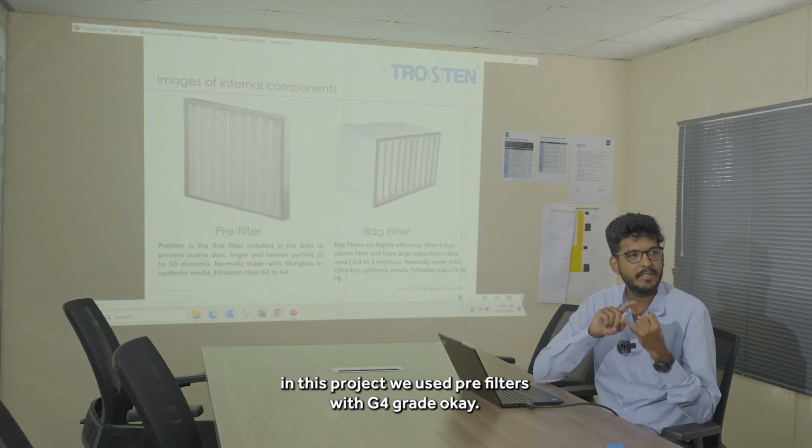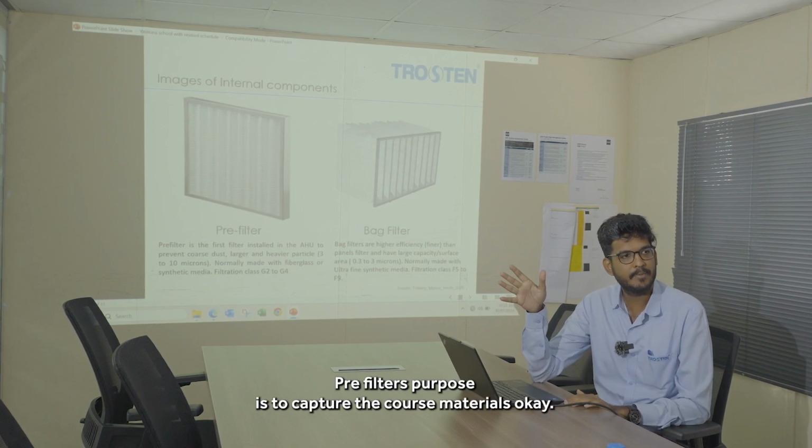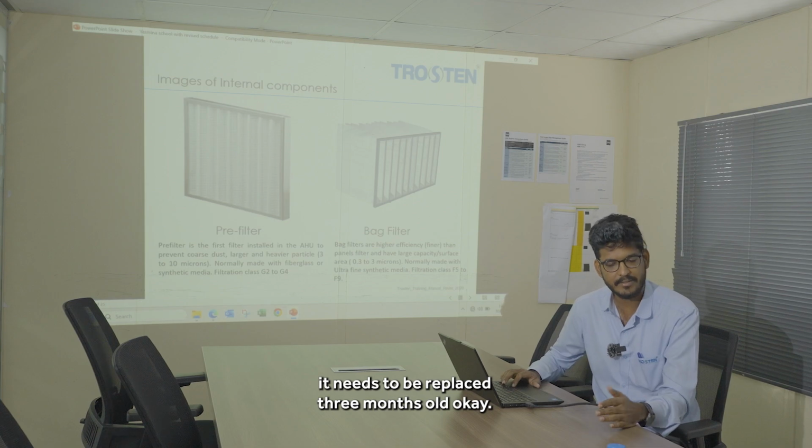In this project, we used pre-filters with G4 grade. The pre-filter's purpose is to capture coarse material. Regarding maintenance, pre-filters can be washed and reused. Back filters need to be replaced once every 3 months.